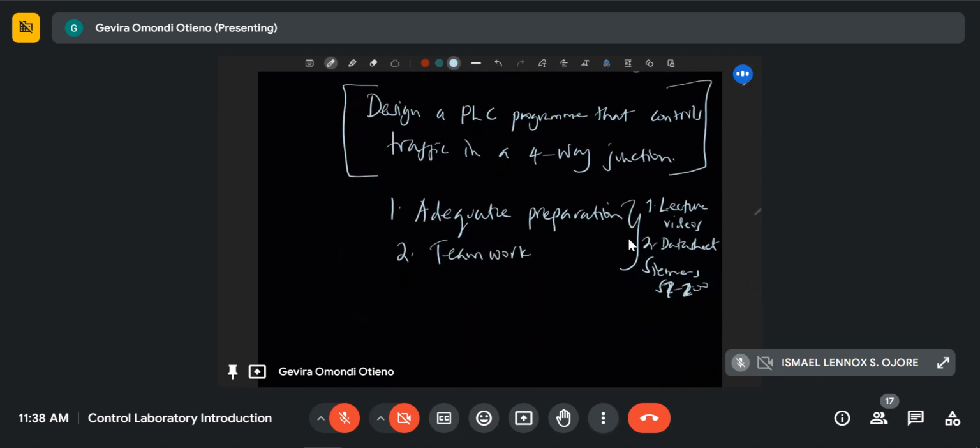So it's called Simatic. Okay, so there's a data sheet for this, and the significance of the data sheet is, if, for example, I want to find a timer, so an on delay timer, an off delay timer, a retentive timer, whichever you want to use, you can go to the data sheet. It gives you a proper illustration of how to get that timer, how to connect it to your ladder diagram, and how to adjust its parameters.